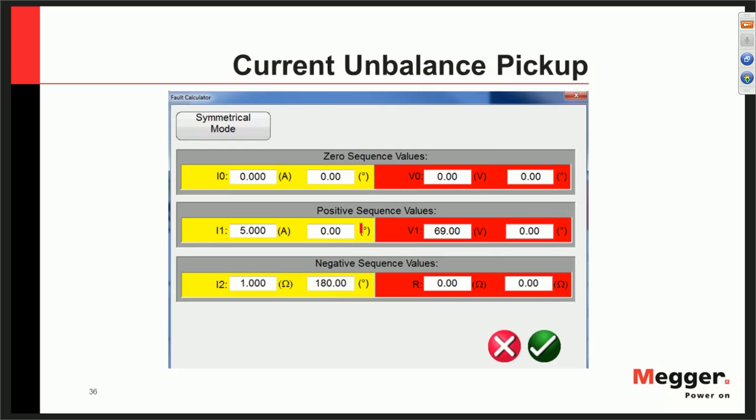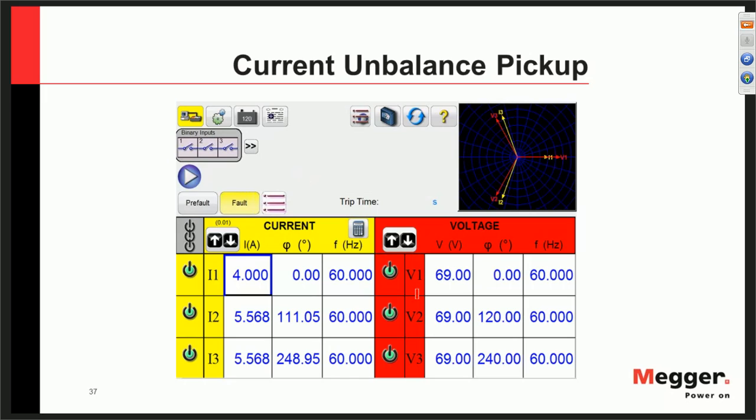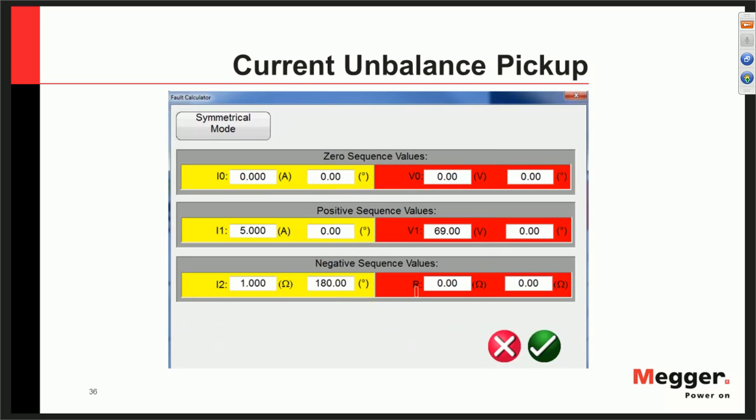Many software packages nowadays are made for the testing of relays. They have a sequence component window, and you can just type in your sequence component values in there and see what my actual phasor values would be. So the software automatically calculates all the mathematics behind sequence components, this whole concept that I showed you in previous slides.